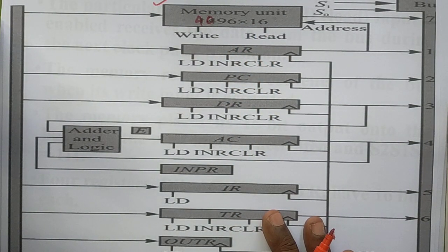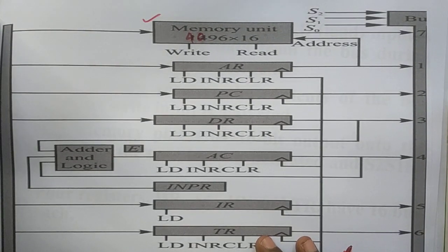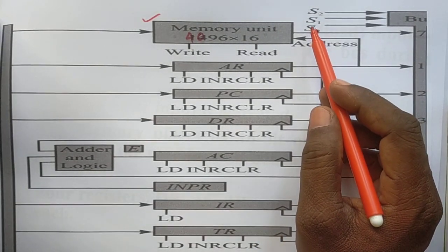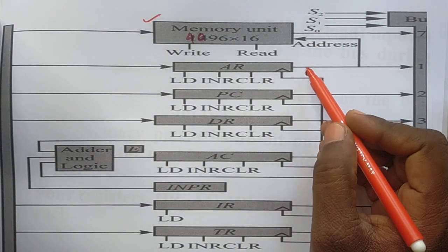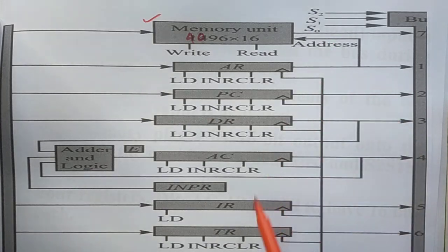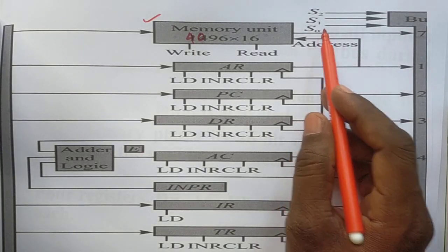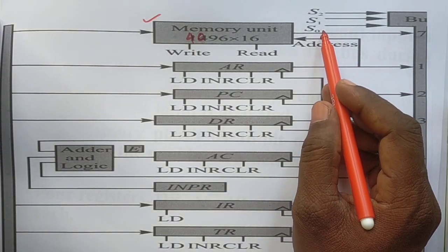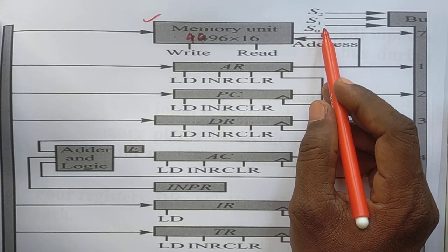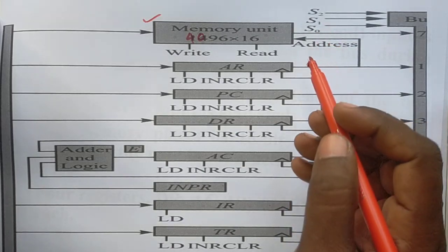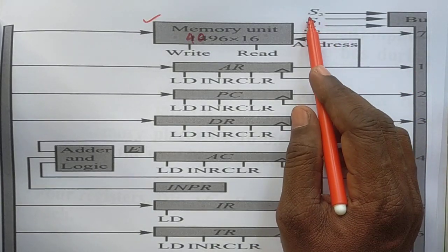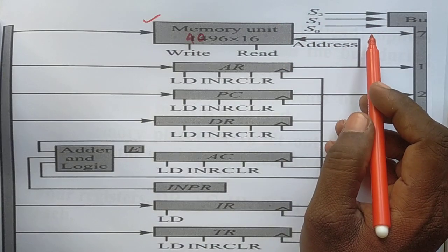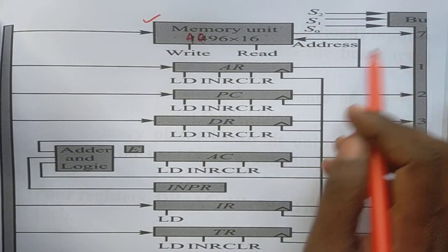And you see, all of you, here I took very simple 3 selection variables, that is S0 S1 S2. Okay, these 3 selection variables are important whenever we design, and these selection variables create a binary number. That binary number also makes a different decimal number. Because the binary number is converted to a decimal number, each decimal number connects to an individual register.